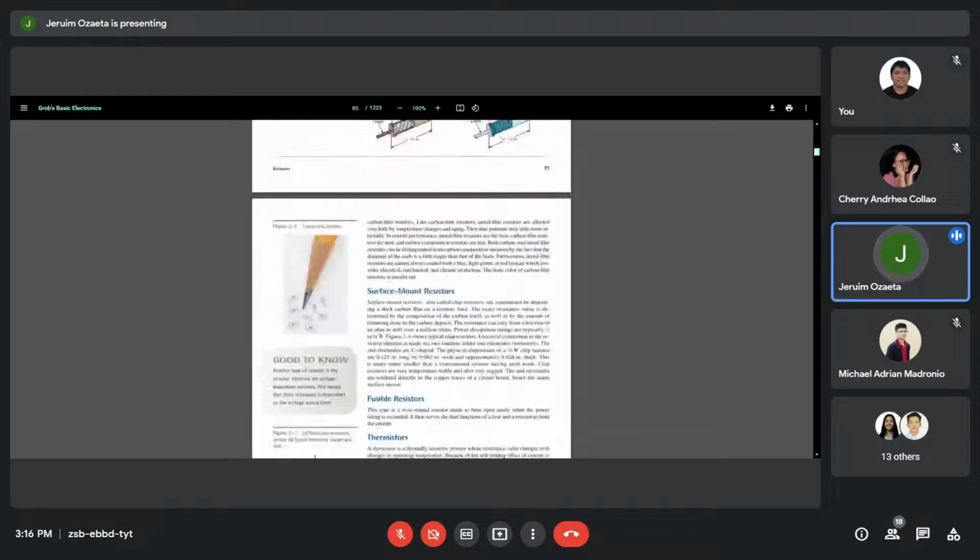A pencil, if you are going to trace, can conduct electricity. That's why if you are tracing a diagram on a circuit on a breadboard that has CMOS, a static sensitive device, never use a pencil, because pencil is carbon, okay? This carbon can conduct electricity and this can cause a short circuit in the printed circuit board.